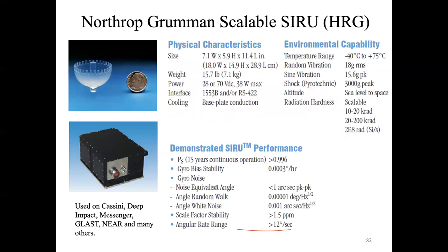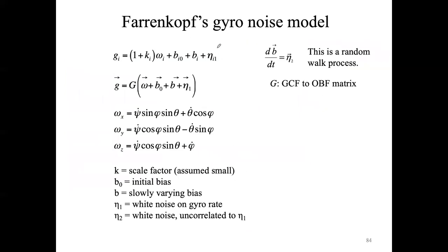If you want to have a comparison with another instrument, it could be useful to compare with the fiber optic gyroscope. As I said, in space, you have a very different thermal environment, especially if you go from cruise to a planet like Venus, Mercury, or others, where you have larger thermal gradients. That leads to variation of the physical length of the fiber optic coils. And this variation over time is indeed responsible for both the angle and rate random walk. So if you want to have a physical meaning of these two parameters, you have to put them in the context of the sensor itself.